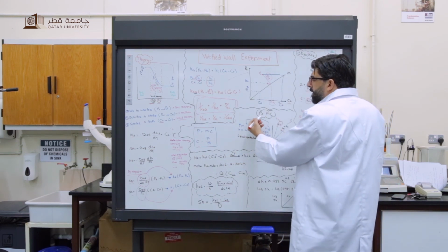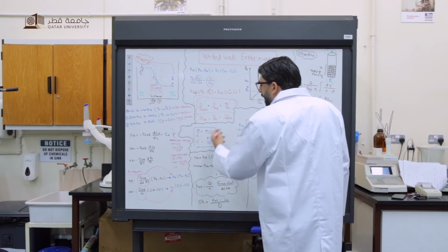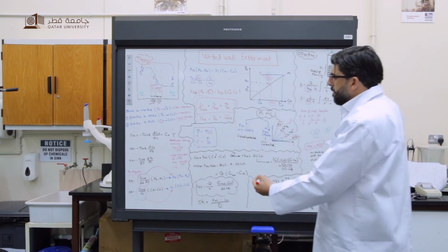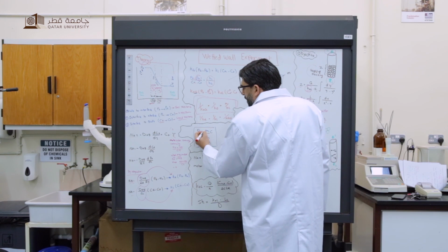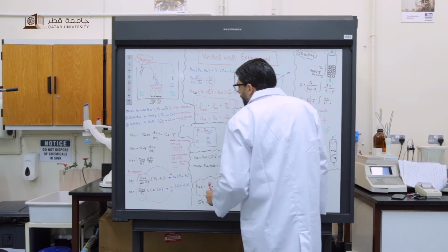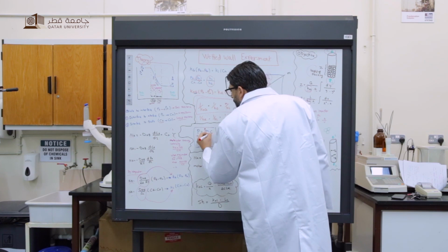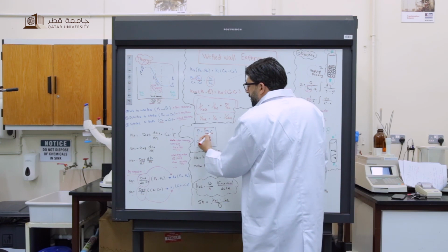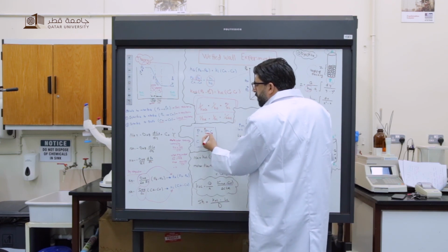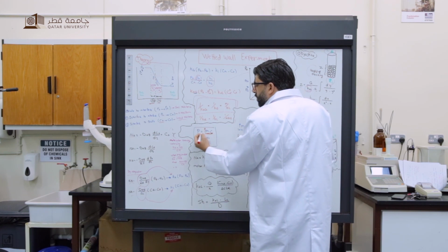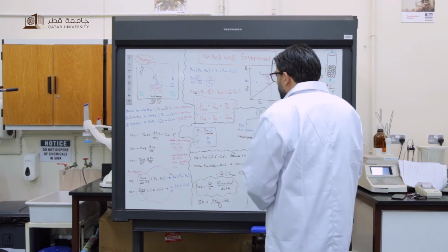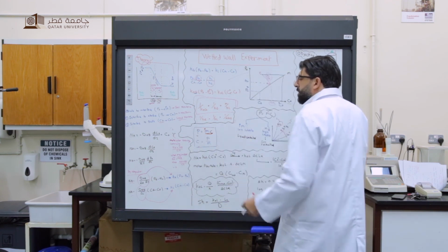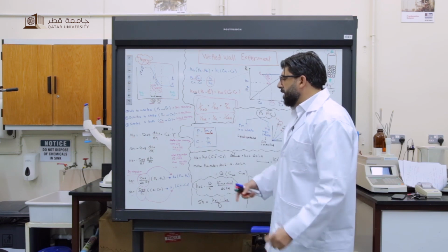Now let's say we said P equals MC, and so C equals P over M. Suppose that M is high. So this part of the equation is significant. When you change the C, it will be significant. That will have an effect on P. So changing the concentration of the liquid will affect the gas phase. So the system here is liquid phase controlled.